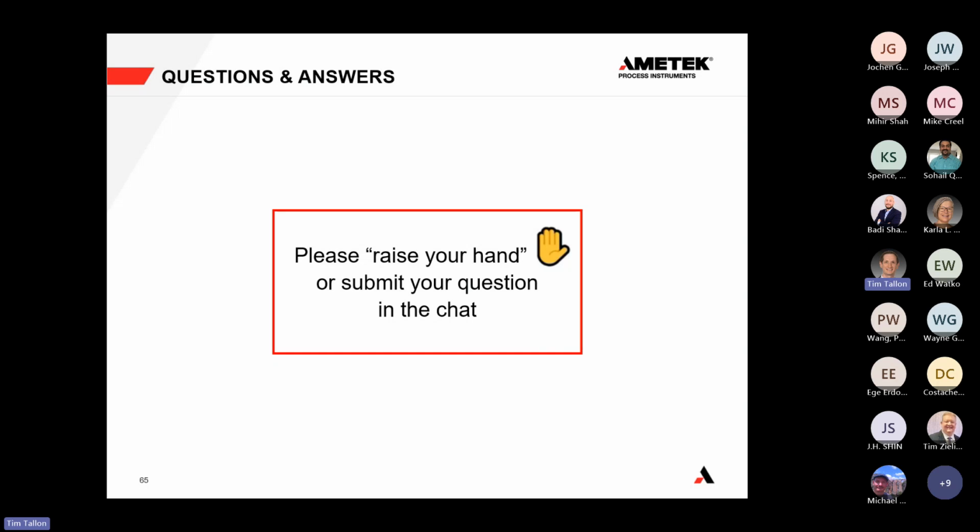Now I see that the second question is, does hydrocarbon measurement apply for all types of combustibles? For coal, for biomass, for bunker? So that's a great question as well. Thanks for asking. The combustible measurement is specifically designed for measuring that incomplete combustion in the form of carbon monoxide and hydrogen, and really anything that's able to react within that reactive zone between carbon monoxide and hydrogen.